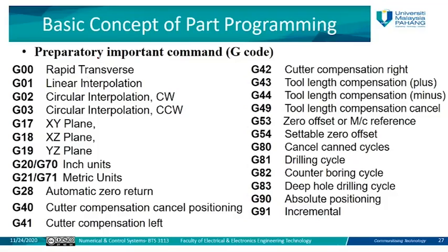Maybe not all, there may be extra G codes, but they are not always used. It depends on the machine, the program, and the task you want the machine to perform. For example, I may use G17 but not G18 or G19. I may use G02 but not G03, or G03 but not G02, or I can use them together in the same program, depending on the requirements of your product or the drawing you have.